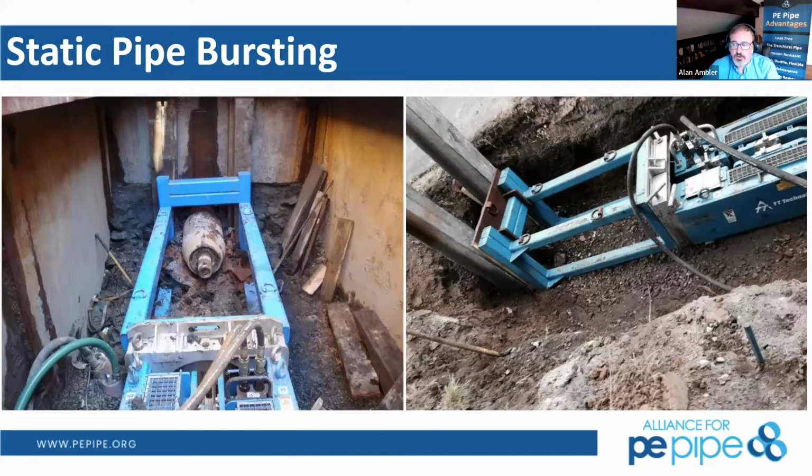Okay, that's a great question. So contractors use many different tools. Sometimes they fuse right onto a swivel that has no opening in that manner. Other times the drill will just enter not all the way through the pipe wall thickness as it goes through. But also, for most potable projects, as we come back through and take that head off, they are going to flush that pipe with superchlorinated water and use a foam pig to push anything that may otherwise have come through during that pull-in process. So there is additional flushing through that.